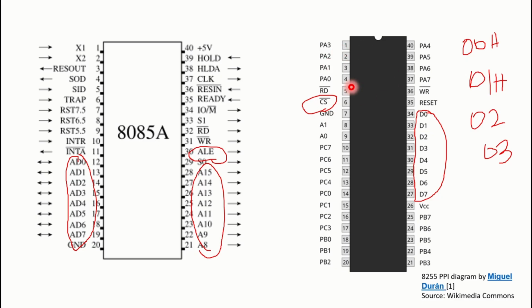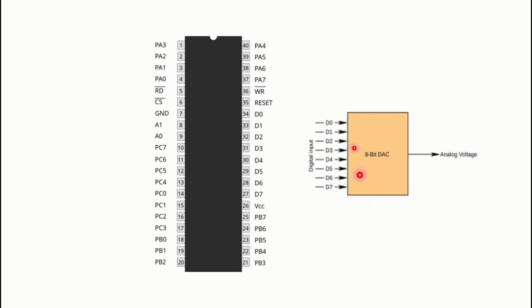So this is connected to the digital input lines of the DAC, which, as I explained, is here actually. Yeah, these are the digital input lines of the DAC, and port A is connected to that. So when a microprocessor writes a digital number on port A, it would directly appear on the DAC input. For example, you can look here. This is the DAC input, and this would directly receive anything that was received by the programmable peripheral interface, which would have received the information from the 8085.